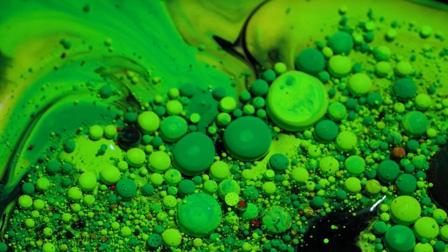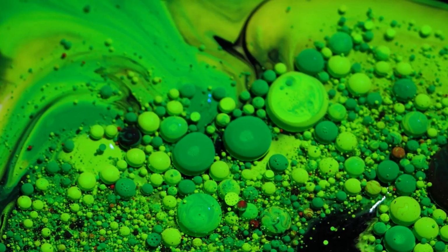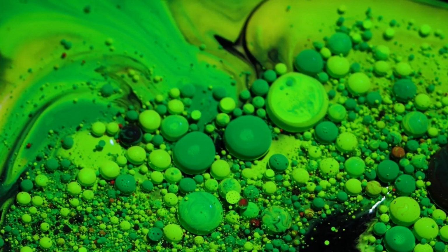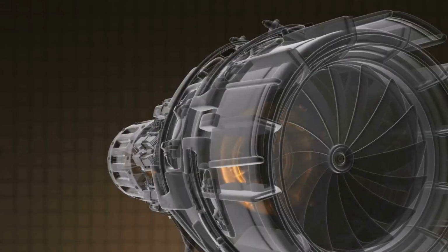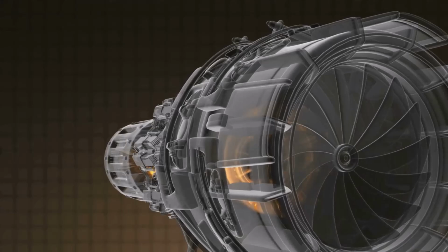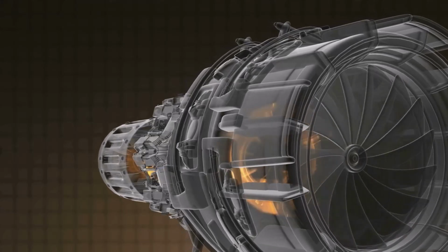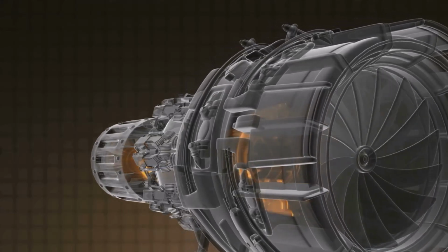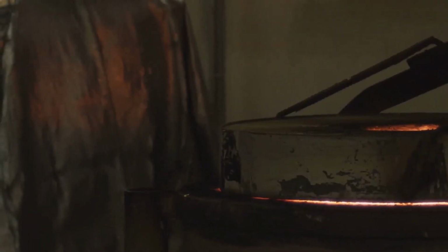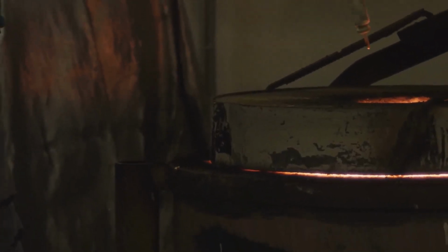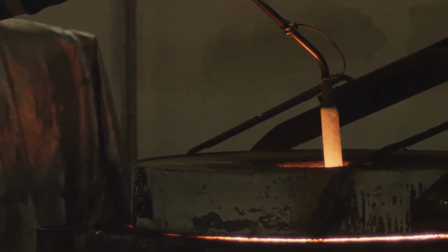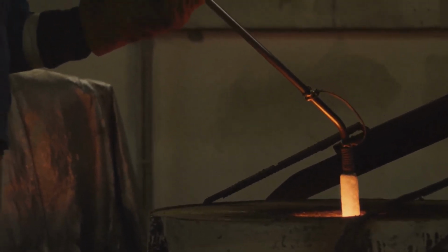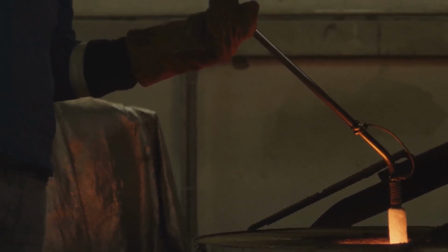It ensures that the very first computational cell of our mesh is nestled snugly within this calm, laminar region. By doing this, our CFD software doesn't have to rely on assumptions or generalized wall functions to guess what's happening at the surface. Think of it this way. If you wanted to know the exact temperature of a hot pan, would you hold a thermometer an inch above it, or would you touch the thermometer right to the surface? You'd touch it to the surface.